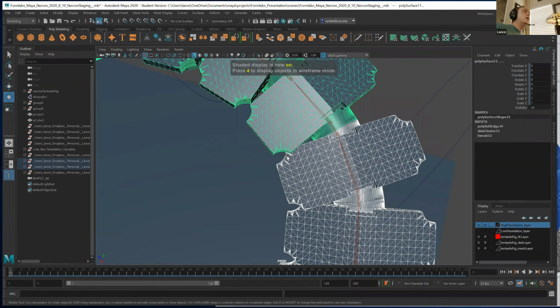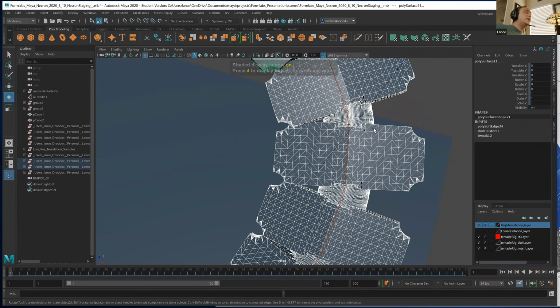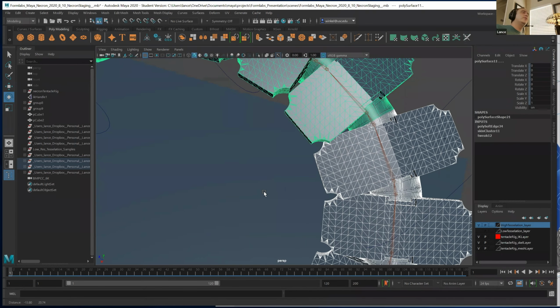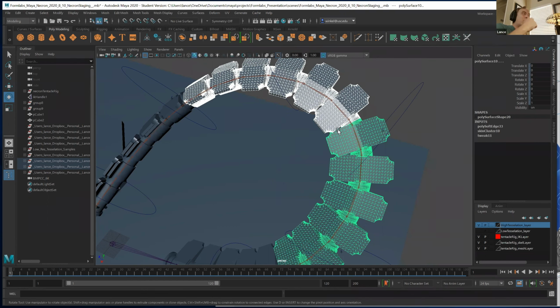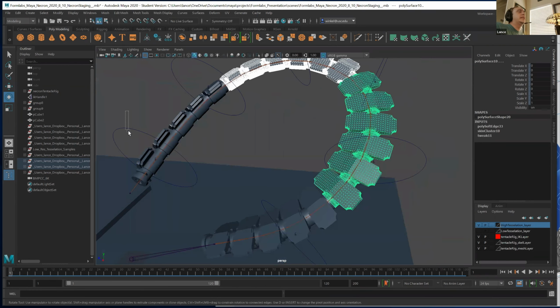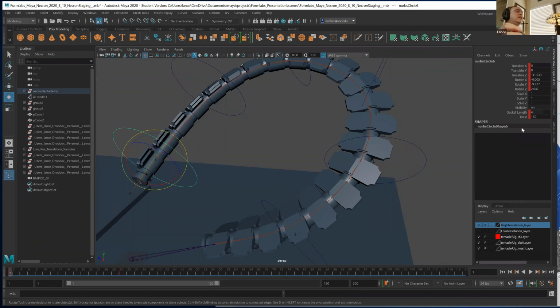So what's going to happen? They're not going to fit. Now this piece, because it's all part of the same mesh, that will just end up becoming kind of a solid sculptural overlap. Okay. I might get an error warning or two from the 3D printer application, but it would still print and print effectively. But areas like this, I would have a problem unless I was to go through and hand sculpt that out. So I wanted to have some mechanisms to help me with this, and Maya gives me that ability. The rigging tools give me an ability. One of the things you can do in spline case is you can actually control the length of the joints.